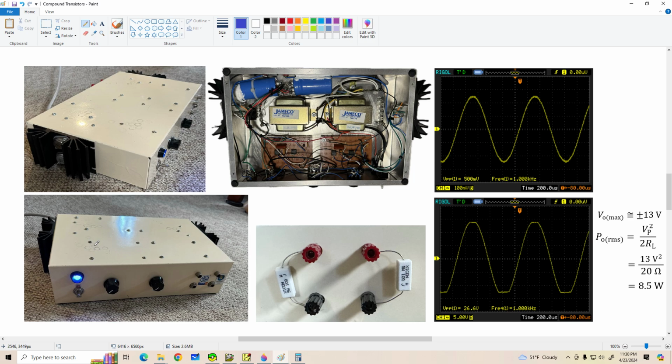All right, now I just set this up and did some tests today, and with an output of 500 millivolts peak to peak, which is pretty small, if we look at the waveform, there are really no hints of crossover distortion at all, so our biasing arrangement is working very well to eliminate the crossover distortion. It's usually worst on small outputs, okay? So that would be where it's most noticeable.